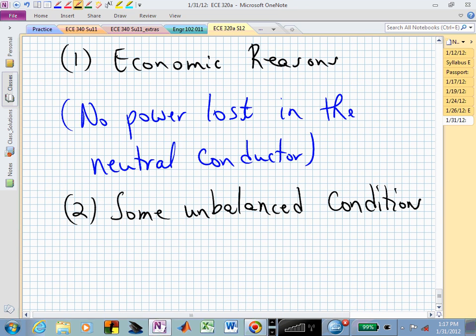and the easiest way to think of something being unbalanced, if we have a three-phase system, we are now saying that the three components of the load look exactly the same. Now you could, in a very crude way, say that's like putting one hair dryer in each phase. Well, now somebody says, oh, I don't need my hair dried, I need to charge my cell phone. So now two phases have hair dryers and one's a cell phone. Well, that's unbalanced. Is that making sense? That unbalanced load then presents more challenging analysis concerns, but in general, if you understand balanced three-phase, you are a long way towards being able to solve or analyze unbalanced load conditions.